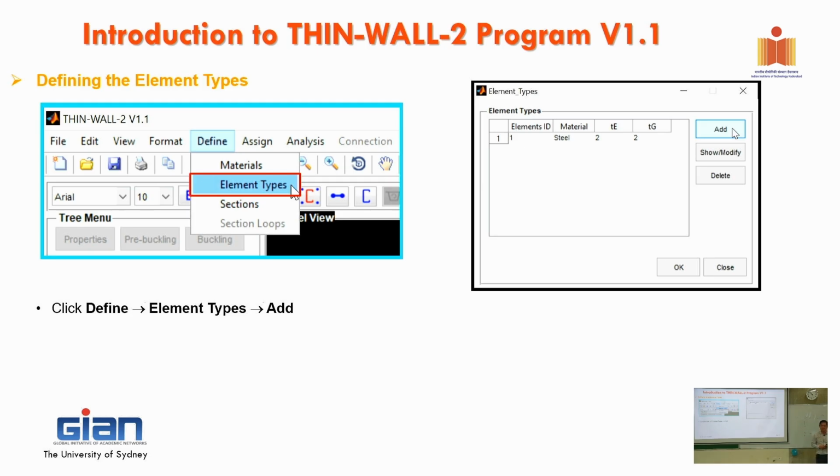Okay. Sorry? How do 2 different materials or 2 different thicknesses become a single section? So you have to tie them together by the same node in here. I show you how to tie them into the node. They're sharing nodes 1, 2, 3, and this one 4, 5, and then this 6. So this strip has to be connected by nodes 3 and 6 to connect those together. I show you how to do it later on, but this is the finite strip. It's actually the strip along the node, and the member thickness is the virtual one.